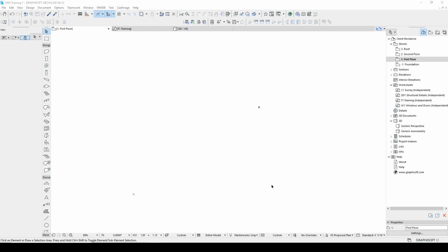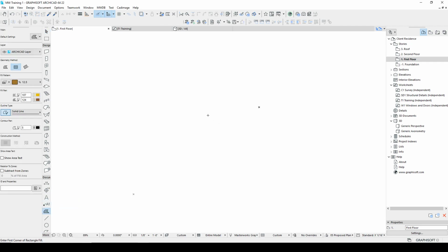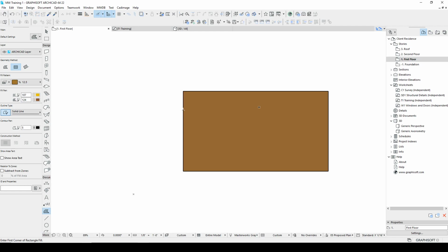Well, now that we've mastered the line and arc tools, we're going to take the next logical step and explore the fill tool. Now, the fill tool is simply a region that's bound. It's a closed shape, and it typically has some sort of fill or vector pattern associated with it, although you don't have to. And I really like the way that ArchiCAD manages these shapes. I think better than really any other program I've ever used, including the Adobe products. It's fluid, it works well, it's smooth, it's accurate, and I tend to use them pretty heavily, and I think you'll find yourself doing the same.